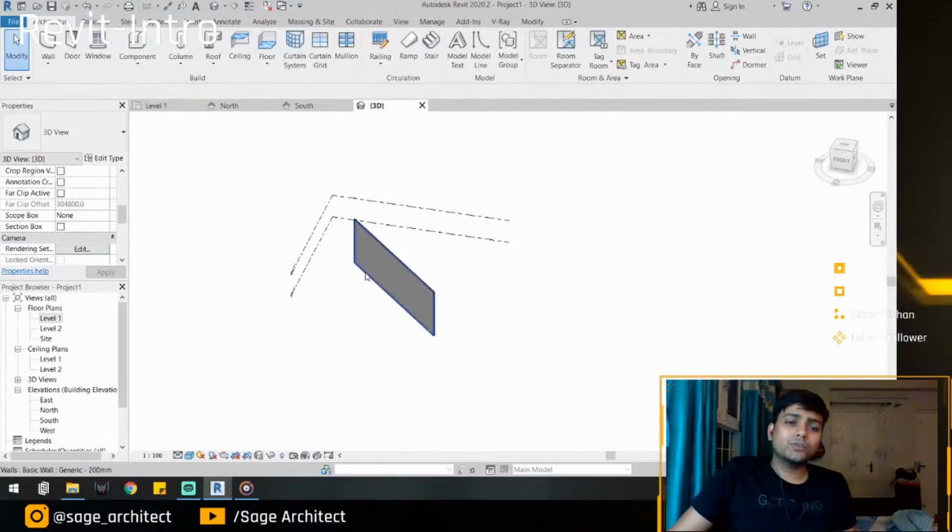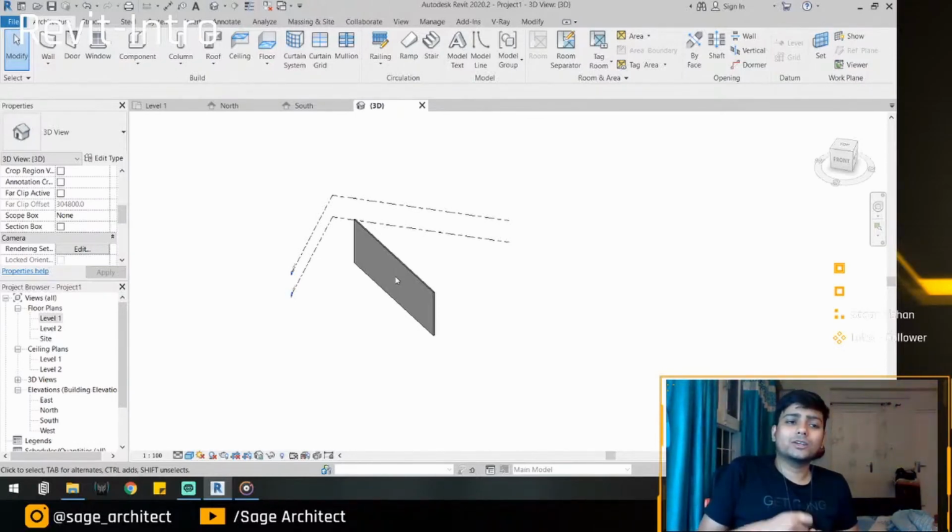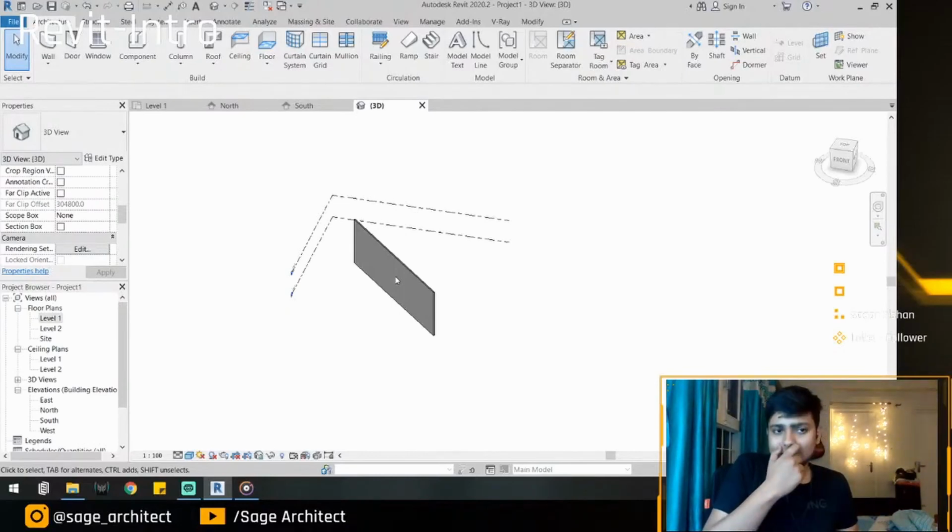Moving forward, LOD 2 will have the quantitative analysis or the room legend. Let's say this is room 1, room 2, area, volume, and maybe let's add quantity into it, like how many doors, how many windows. And moving forward, the level of detail starts increasing. We get more into depth. Let's say we are using M20, so how much concrete, how much fine sand, how much coarse sand, how much water.